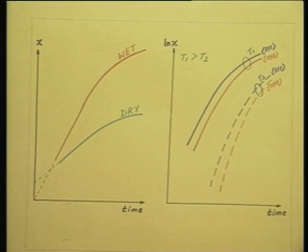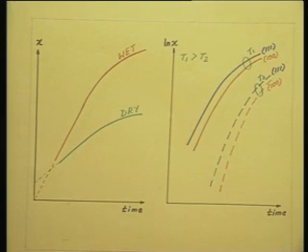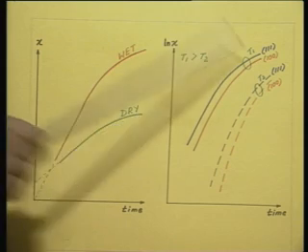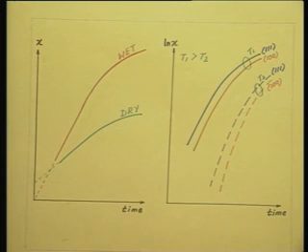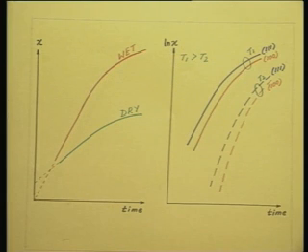But now I have added another twist to this, that is I have plotted the curves both for 111 and 100 oriented crystal. And you see that the 111 oriented crystal shows a higher rate of oxide growth than the 100 oriented crystal. This is true for T1 as well as for T2.